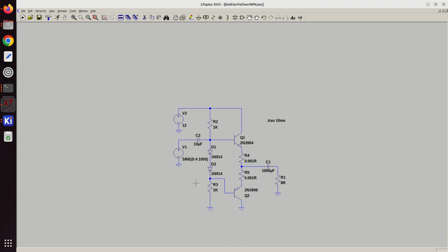So now the idea is that the signal will come in, or sorry, we look at the setup here. So we have current flowing down here, and then we should have approximately 1.4 volts drop across this here, and current flows down to ground here. So if we look at the midpoint here, this should still be at 6 volts. The output should be at 6 volts.